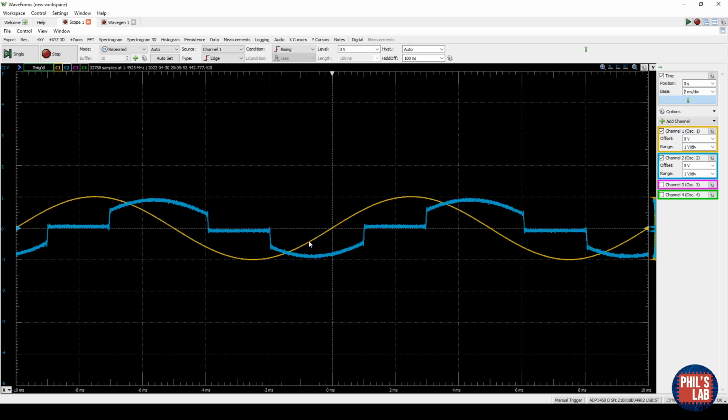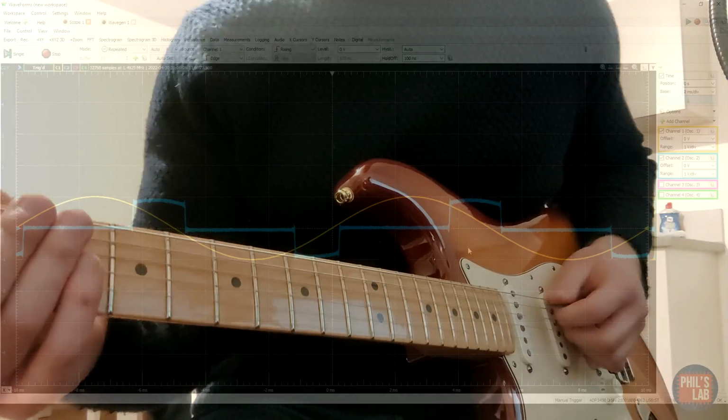You can see here there's also some time delay because of the processing. I can increase the threshold even further, and then we let through only very small amounts; the magnitude of the signal has to be very high for this noise gate to pass anything. So a very simple noise gate seems to be working. Now let's try listening to that with some audio and see that this doesn't sound very nice.